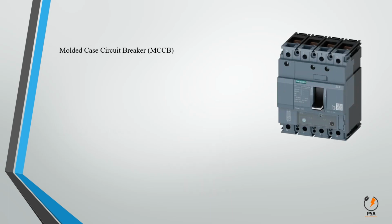Molded case circuit breaker. The molded case circuit breaker is a circuit breaker with a high current rating of up to 2500 amps. They are generally used where the current exceeds the limits of the MCB or miniature circuit breaker. This circuit breaker uses a thermal magnetic trip mechanism, with the thermal mechanism used for overload and the magnetic for short circuit. It can quickly dissipate a current of about 200 amps. They protect devices such as generators, electrical supply lines, capacitor banks, motors, etc.